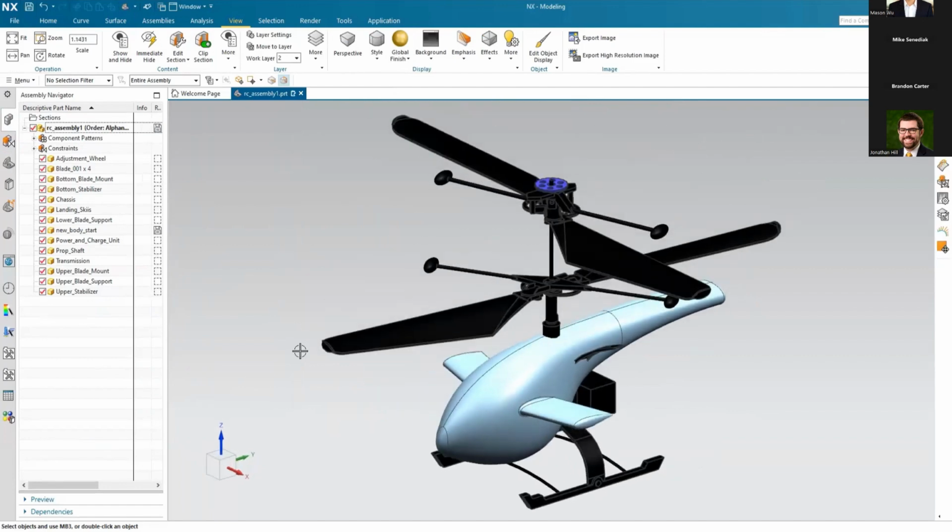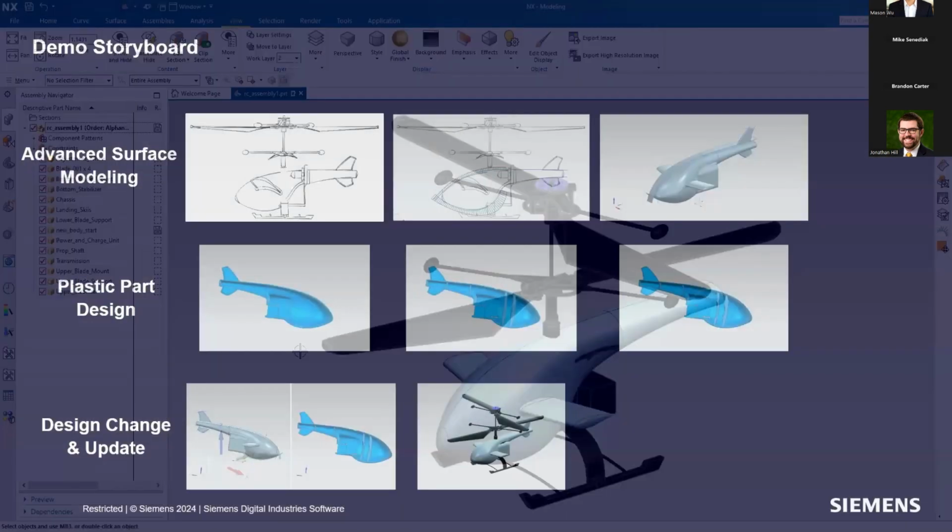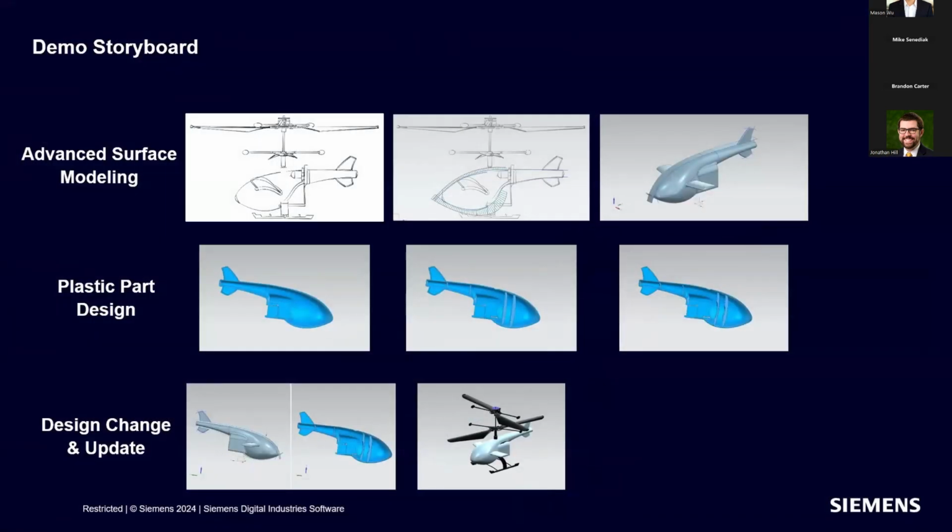We see that we've been able to generate the shape. And so we could continue on with more using some more things from the reuse library, but I think that gives you a good idea up front using the curves to generate, whether those be splines, whether those are sketches, how you could do surfaces only, how you can do a combination of solids and surfaces to create, trim, do all of those as you work through.